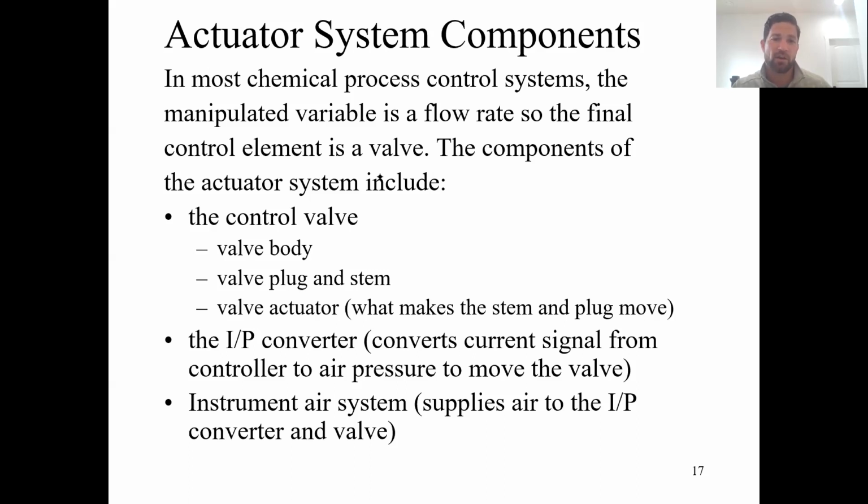So there can be electronic components used to change the manipulated variable instead of a flow valve. For biological processes, oftentimes there are variable speed pumps where you can change the flow rate by changing a setting on the pump, and all these are electronic types of control.